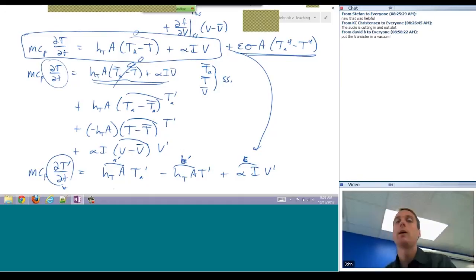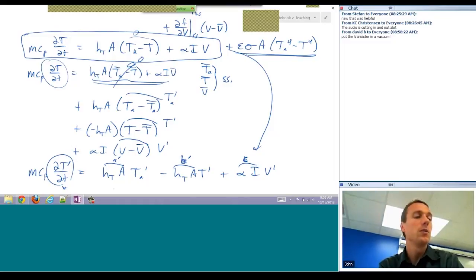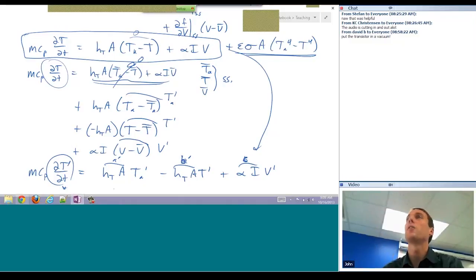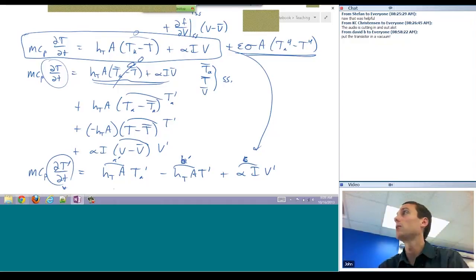So once you have these, the assignment was to derive a first principles model between input voltage and output temperature, simulate the first principles model, compare the results to the data that were collected during the doublet test, and then adjust the parameters to align the two. You can first just start with your best guess of heat transfer coefficient, your best guess of mass, C_p. Just try to put values in, simulate that against your measured values of the device, and see if they match up.